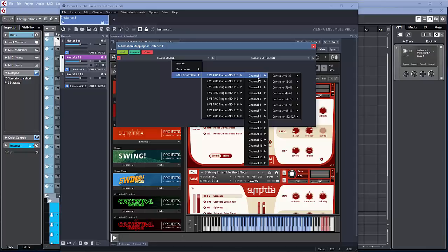There's no magic there. Just do a bit of homework. Make sure you're not picking CC1 or something that's used by loads of stuff. And there's hidden stuff in the MIDI spec. So go to the MIDI spec, find a blank one. If you want one for free, try 19. It's worked for me. So there you go. Channel 1, control 19.